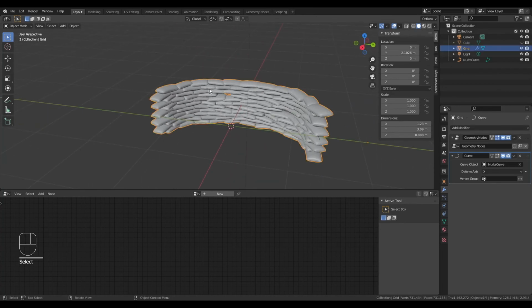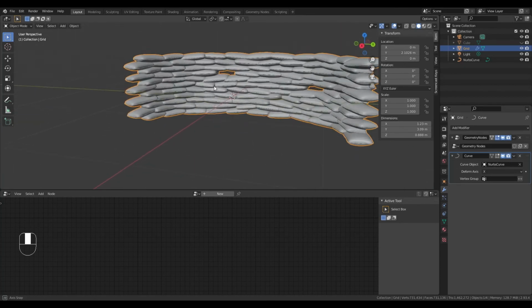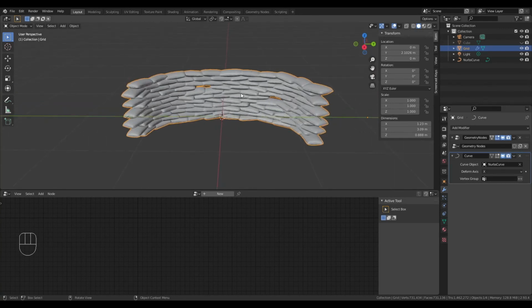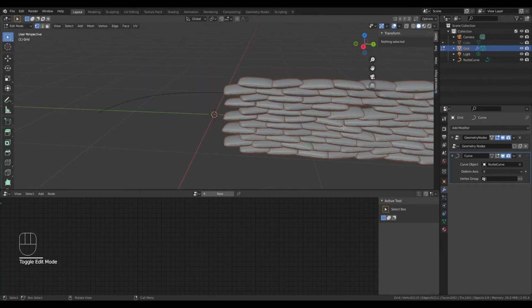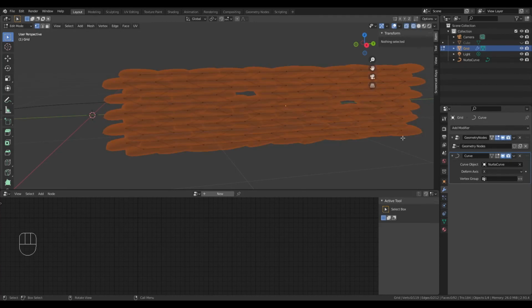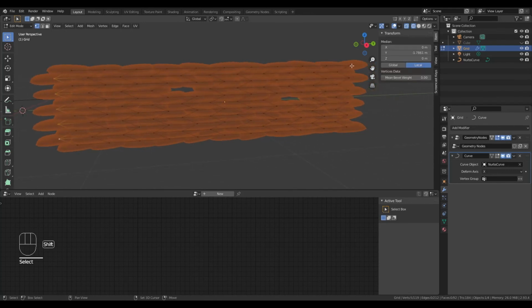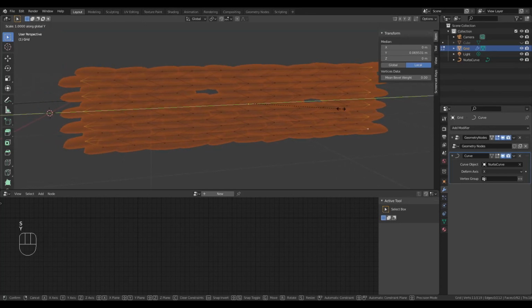Now another problem I see with this wall is that it has these sort of end bags hanging off that we don't necessarily want. I'm going to fix that in probably the laziest way possible. I'm just going to go from object mode to edit mode with the sandbag wall selected. I'm going to change to wireframe mode so I can see individual points. And I'm going to select the points that are on the end. And then I'm going to press S for size and Y so that I can size them on the Y axis. And that'll bring them in and out as I move my mouse.